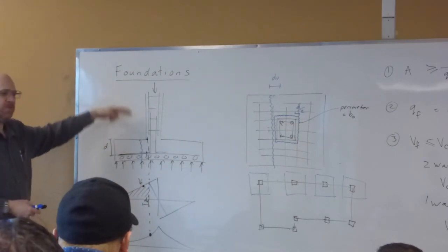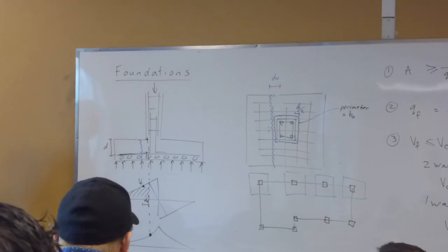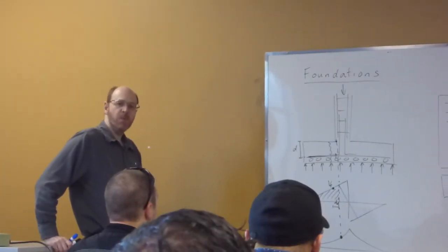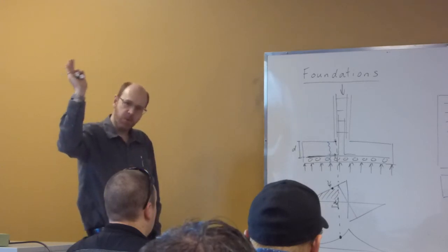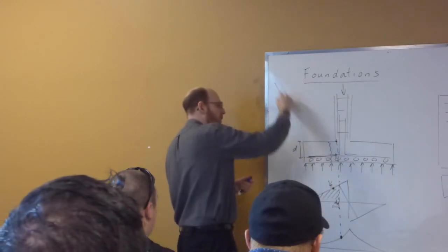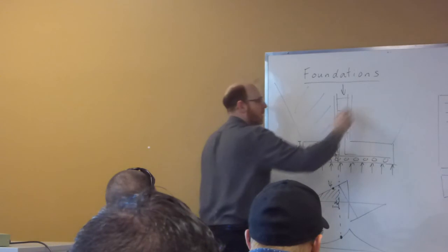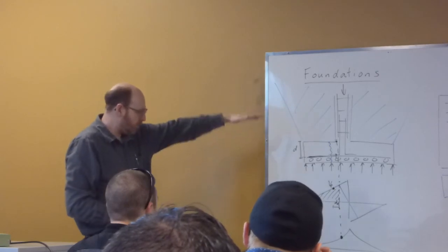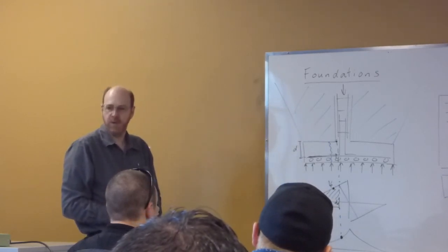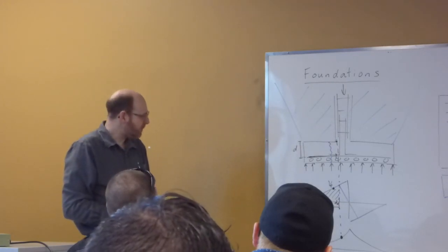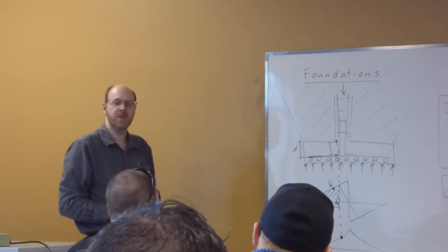What we haven't talked about is the depth of this footing. And the depth of the footing can actually be critical. When we're talking about a tall building, the overturning moment on the building, as I apply an earthquake or wind force, is trying to push the building over. And what's resisting it is this footing being pulled up, and it's mobilizing a whole bunch of soil sitting on top of that. So if we think that there's a possibility that the building's going to get knocked over, what we want to do is put the footing deeper so that I can mobilize more soil. And typically we're looking at a 45-degree angle, but it depends on the soil properties. So there's the depth side associated with it as well.